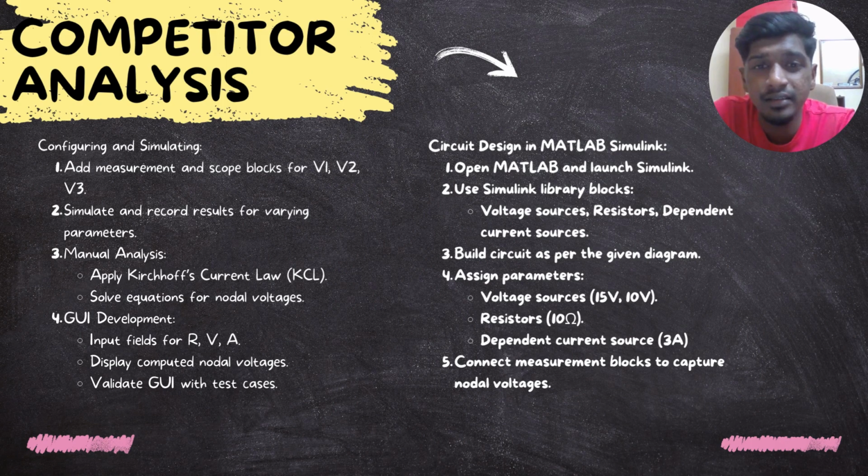The second analysis is circuit design in MATLAB Simulink. First, open MATLAB and launch Simulink. Use Simulink library blocks such as voltage sources, resistor, dependent current voltage. The third thing is build circuit as per the given diagram.